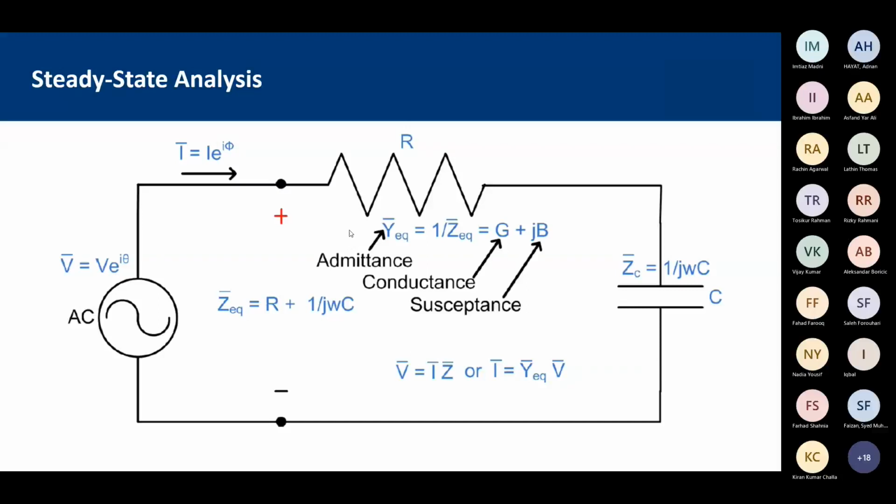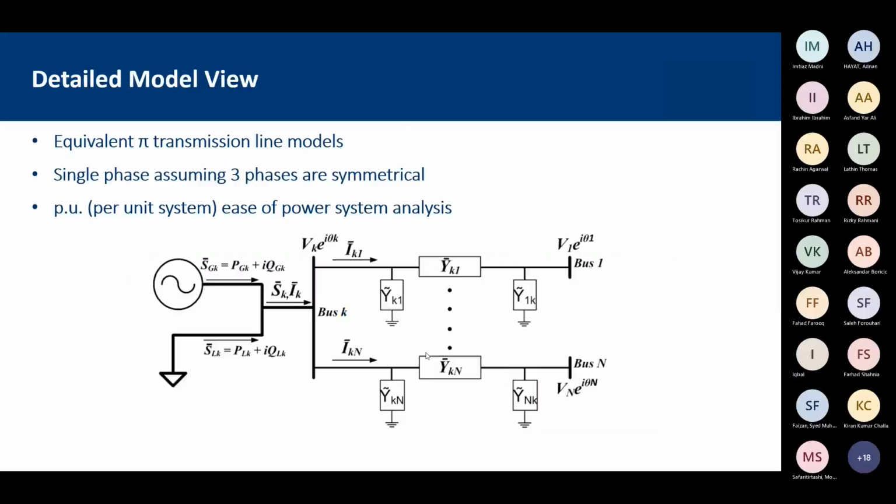And as I said, these days we model the transmission lines as PI models, and then we have the load parameters and the capacitors or compensators. This is what we used to do conventionally for conventional power systems, modeling generation sources and then the distribution and transmission lines.